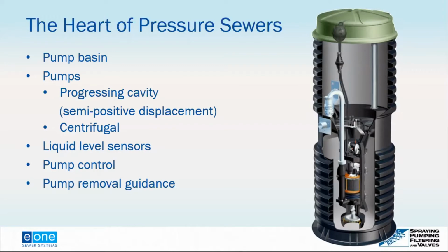When looking at pressure sewers, there are going to be different manufacturers, but they're all going to have pretty much the same components, where you have the pump basin, and within the pump basin you're going to have your pumps. Those pumps could be either a progressive cavity, semi-positive displacement pump in the case of E1, or a centrifugal pump.